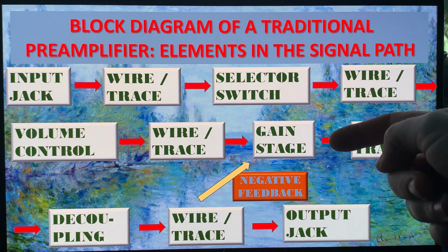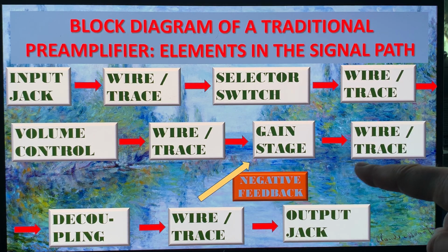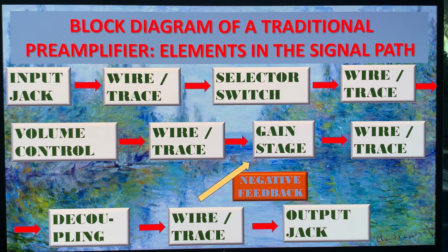When such a simple approach requires negative feedback, it's to make the unit compatible with all the junk on the market. If you have a system where one unit is matched perfectly to the next, so your preamp is matched perfectly to your power amplifier, then you do not need negative feedback here.